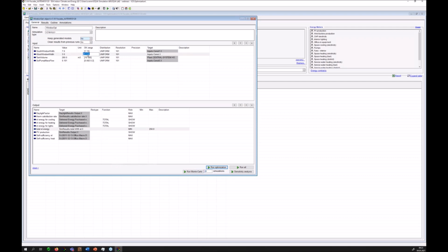You can then look at these results and adapt your input parameters. So you can adapt the ranges here, for instance, and you can exclude some goal functions and include others if you want. You can set constraints and then restart your optimization. Just don't forget before restarting to clear results from previous runs, in order that your optimization routine doesn't forget what it already calculated.